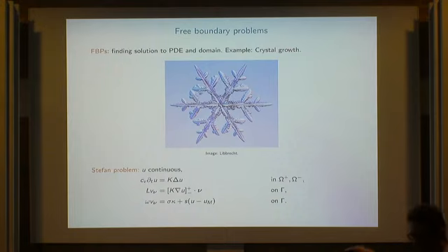Now you need an additional condition for the free boundary. That's this last one, the so-called Gibbs-Thomson condition, written in such a way. Again, the normal velocity features up to some kinetic factor. On the right hand side, we have two terms. I mentioned that if we cool the system, we would expect the solid part to grow. That's incorporated by this term. If we have a deviation from the melting temperature, then we should see some evolution of the free boundary. But there's also a capillary term.